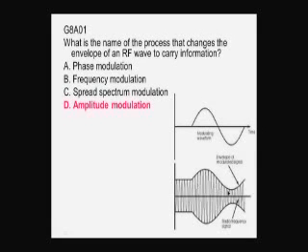and here the amplitude of the carrier, the power in it, the height of it, is being modified by the modulating waveform. And the envelope is the outside shape of it. The only way to modify that outside shape is by changing the power of it, or changing the amplitude of the wave. And so if we modify the envelope, we are using amplitude modulation.